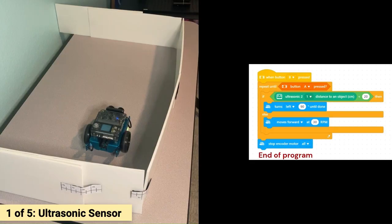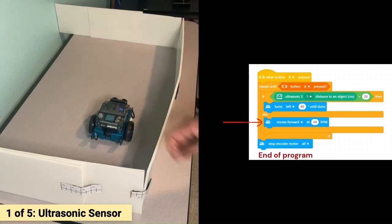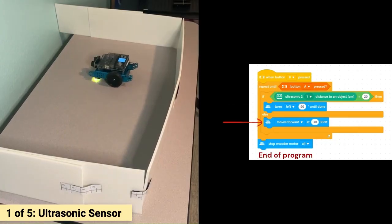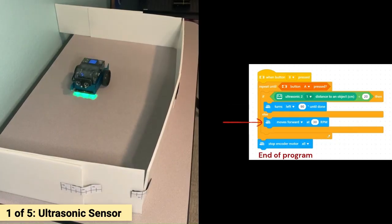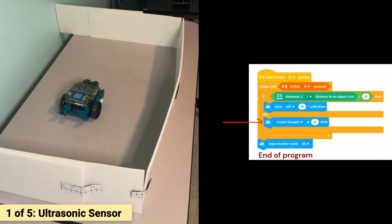We're going to start our program by pressing button B. We see the robot continue to drive straight until an obstacle is less than 20 centimeters away, and then turn left by 90 degrees, and this process repeats.